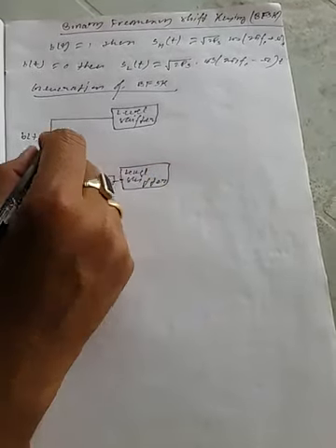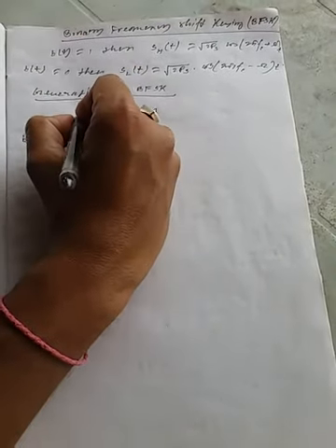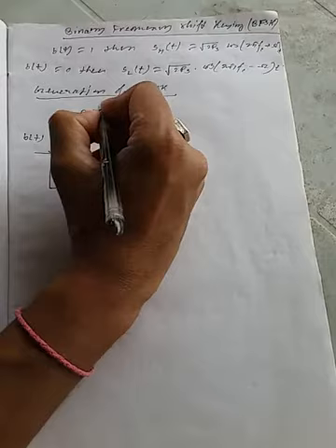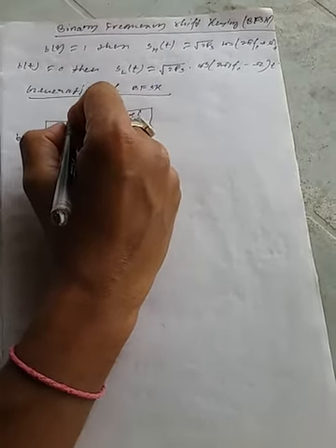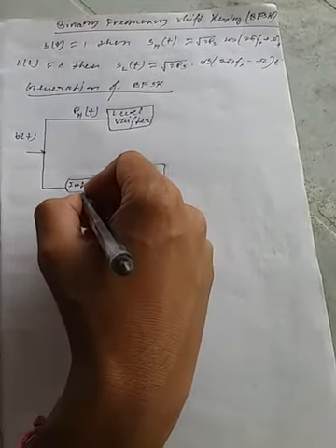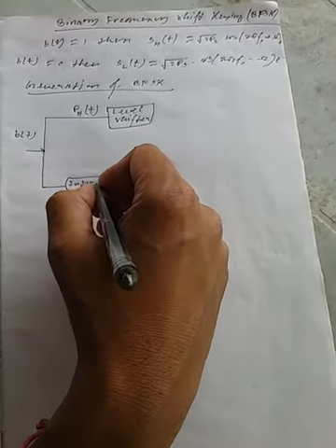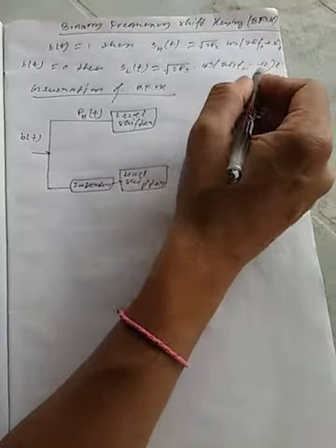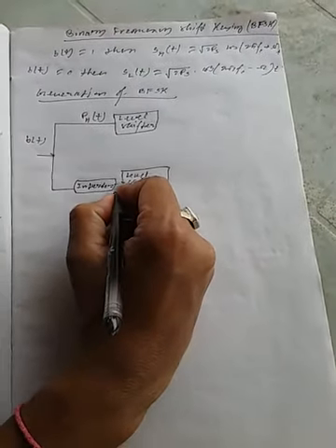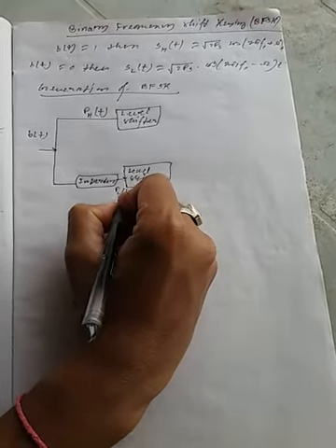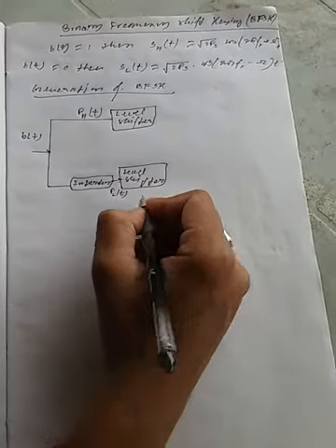If the symbol is high, this generates a higher frequency signal that can be represented by PH(t). The inverter inverts this to the lower value. The output of this inverter can be represented by PL(t). So this is basically the lower frequency signal.